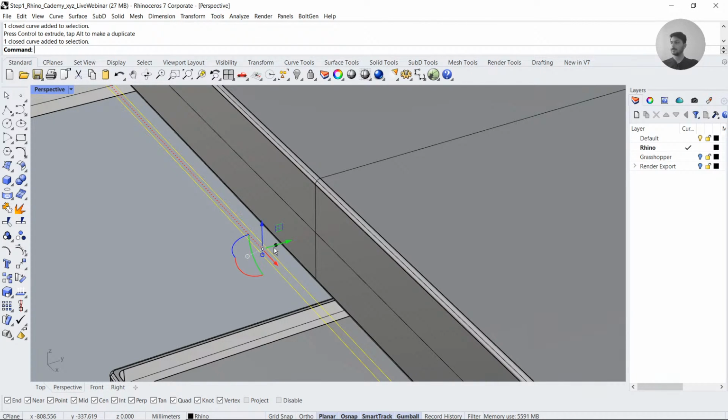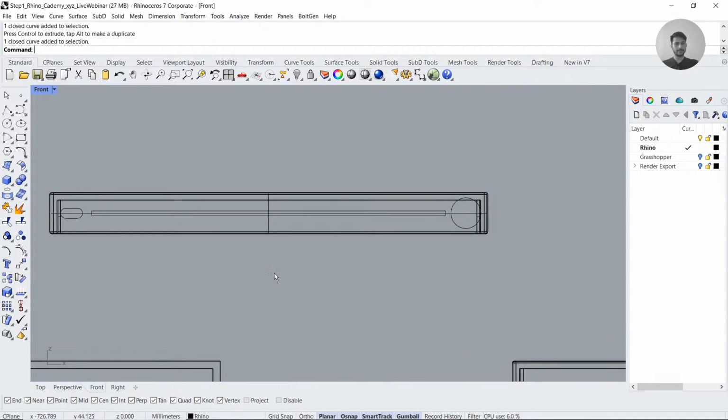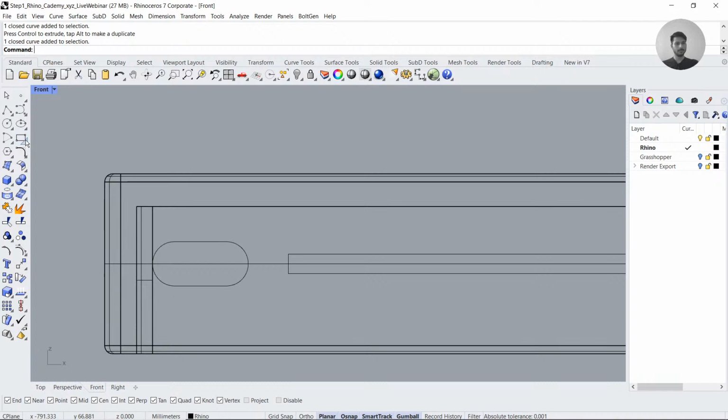How did we make the curved rectangle? So to make the curve rectangle, you have to go to the rectangle tool, rectangle from center, and here you select that it is going to be rounded. Okay, you mark that it is going to be rounded, and now you can start 6 by, I don't know, it was 1.7 units or something else, and then you can change the dimension by moving the mouse cursor to the center.